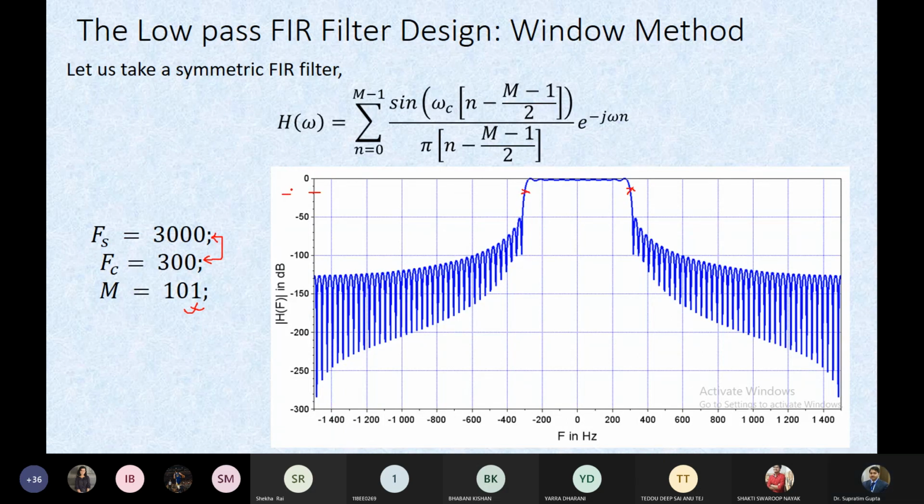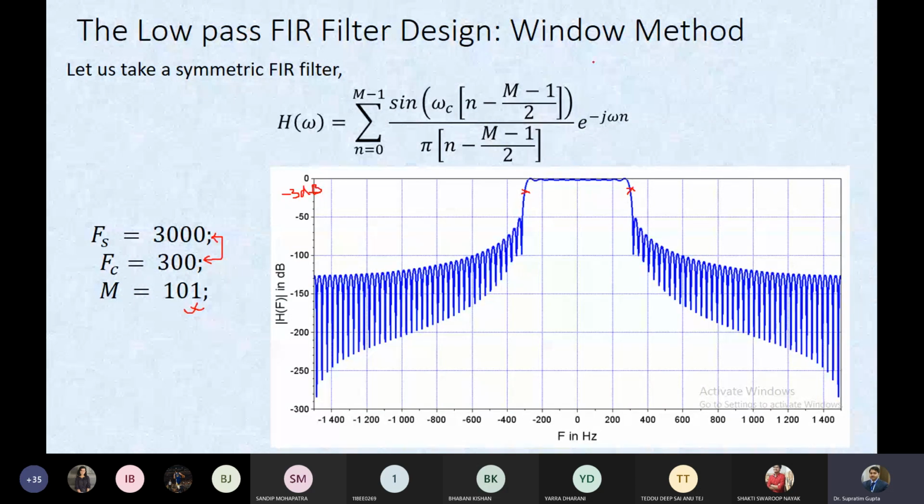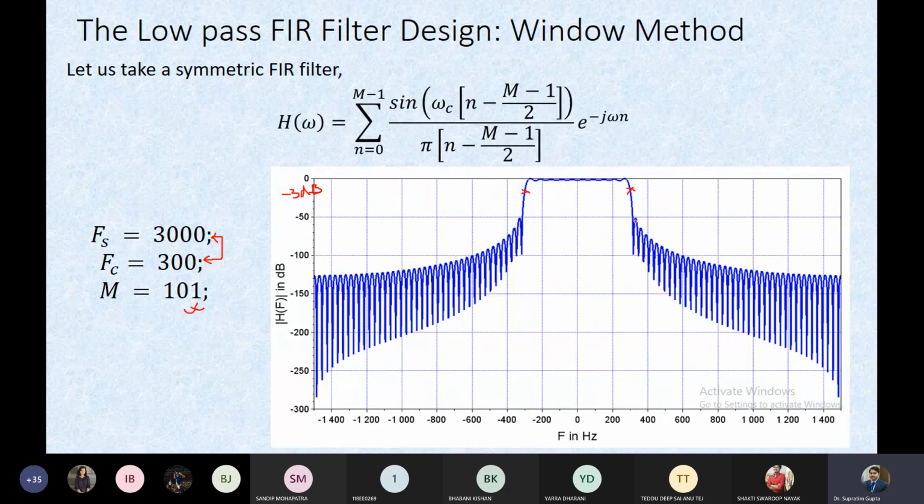And then the side lobes are very low, starting from minus 50 and going lower. Now, earlier we took the rectangular window, we just truncated. But what happens due to this truncation is that the continuity in the time samples is lost, and because of that we get side lobe components which are non-zero, as well as oscillations, which might have significant values in some cases.